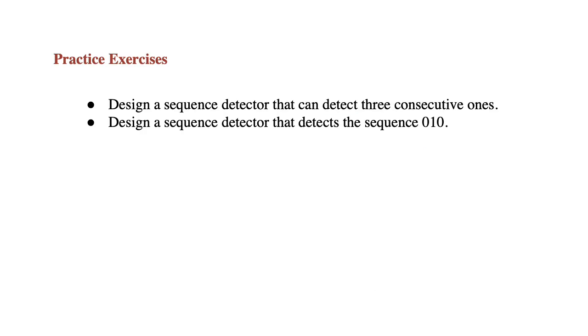In this slide, you'll see some practice exercises. We've already explained how to design the state diagram for these sequence detectors, but feel free to create the state tables and the K-maps to obtain the expressions and then sketch the circuit diagram for these detectors.